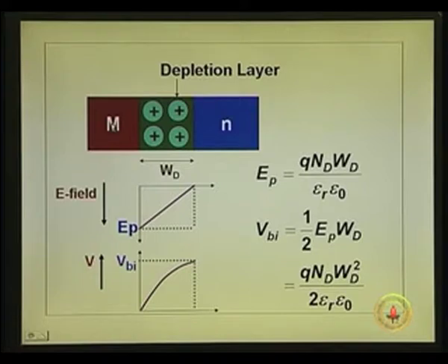So, just like in the case of p-n junction, where p you have got the metal there, all the depletion layer is on this side. If it is p plus, there is no depletion layer. If it is metal, there is no depletion layer here. The electric field actually is plus here, minus there, from right to left. Okay. Now, by solving Poisson's equations, you know that the electric field will be linear, peak at the junction, and linearly decaying, it is 0 at the other end of the depletion layer.